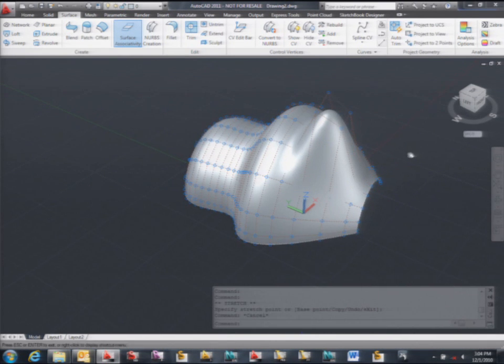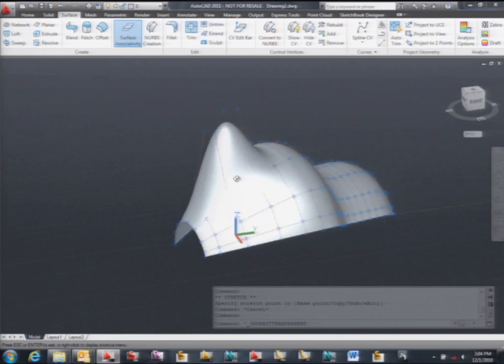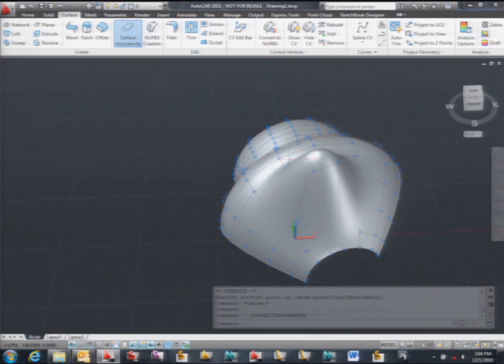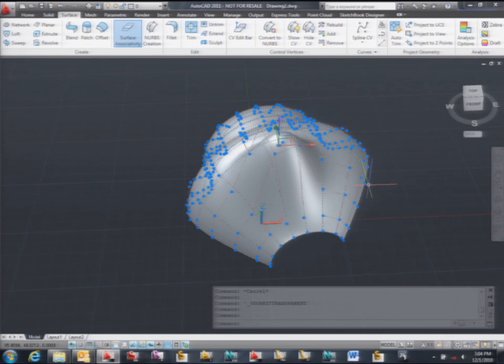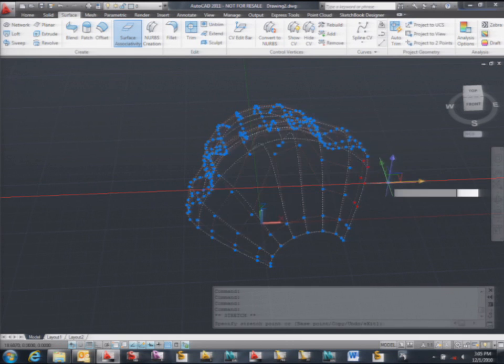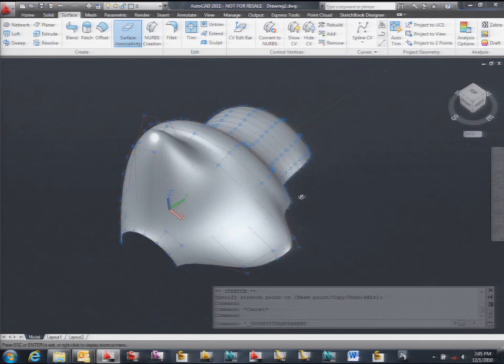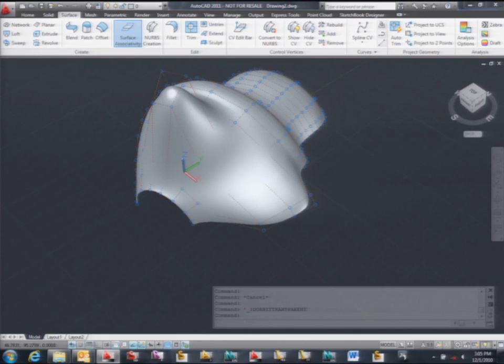This is the kind of thing that you could never have done on a revolution, because we cannot describe this part with a revolution, right? Or you could have maybe needed to expand these six here in this direction for some reason, right? So everything still has G2 continuity internally, it's fine, but you get this kind of behavior.